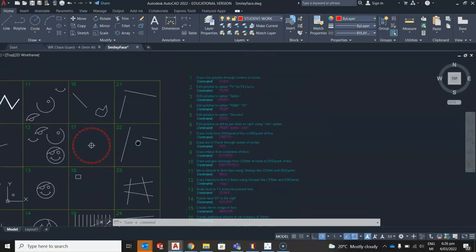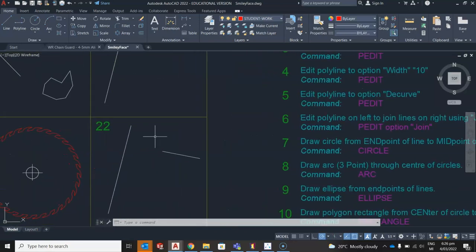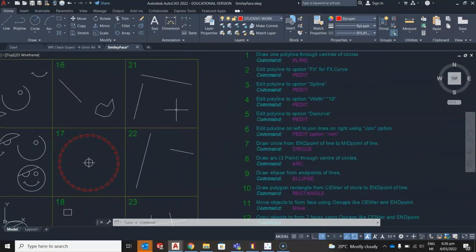So chamfer and fillet. A chamfer is a straight edge or a flat surface that is at an angle to something else, often used as a lead-in in a production scenario where you have components following a conveyor and you don't want them to catch. Or it could just be to break a sharp edge.